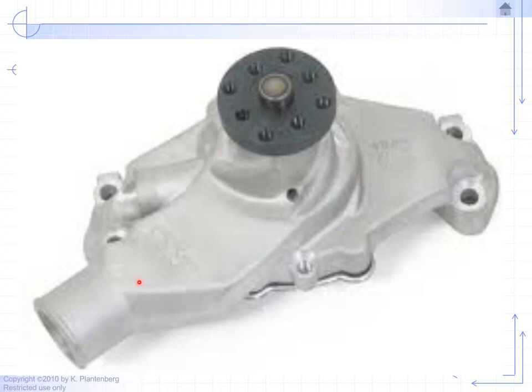Once you come up with a rough shape from the mold, then you can go ahead and do some machining. You can machine the hole, for example, here where the water hose attaches. You can machine the bottom where you have this foot, and you have another foot here. You machine it so these two surfaces are parallel and coplanar, and then you can mount to the front of the engine block. And you want a nice seal. You don't want anything to leak as far as water coolant.